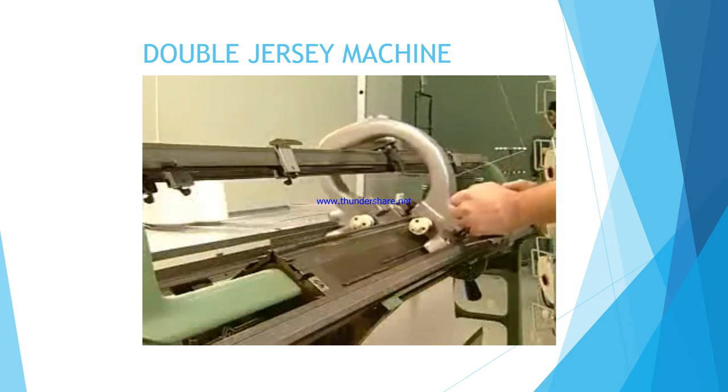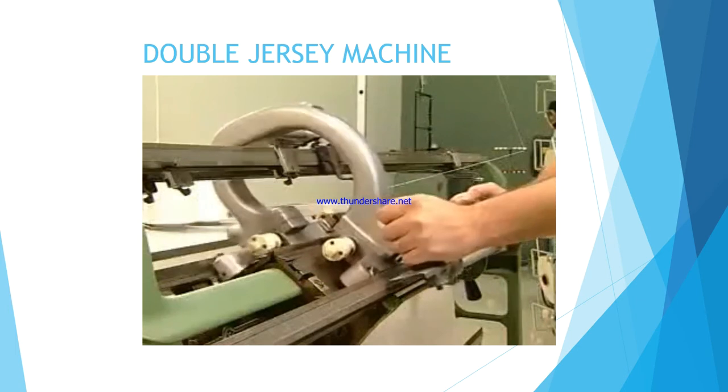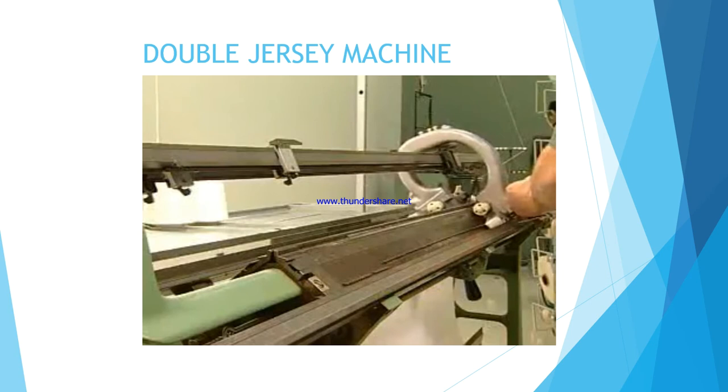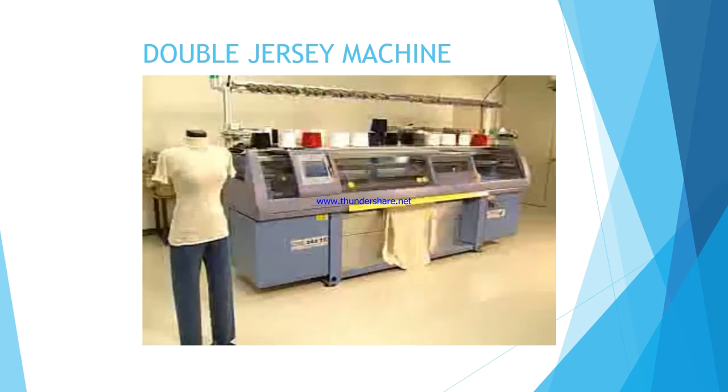Another type of weft knitting machine, designed to make single and double knit fabrics, is a flatbed machine. These machines may have the two needle beds in the same plane, but usually they are set up in a V configuration and then referred to as V-bed machines. These knitting machines are used to produce tubular fabrics or flat panels that can be put together to form a garment. Because the width within a panel can be made to vary, this system minimizes waste and sewing. Also, the technology has matured so that a complete garment can be made on this machine.